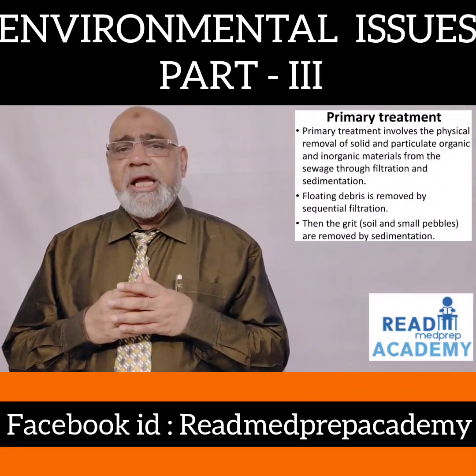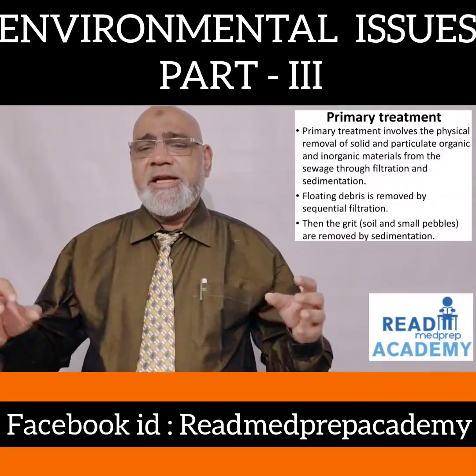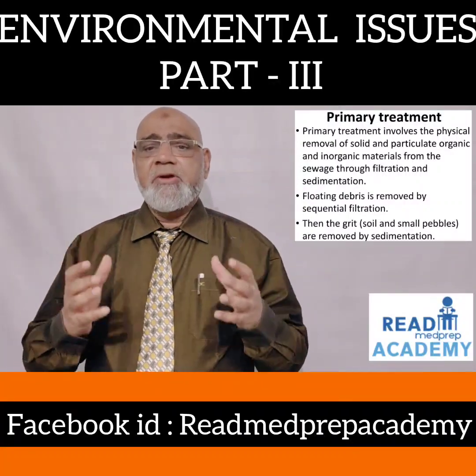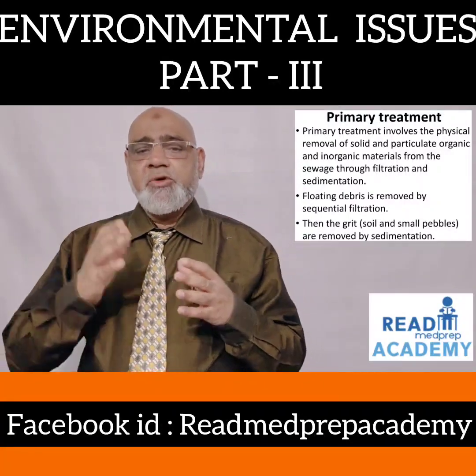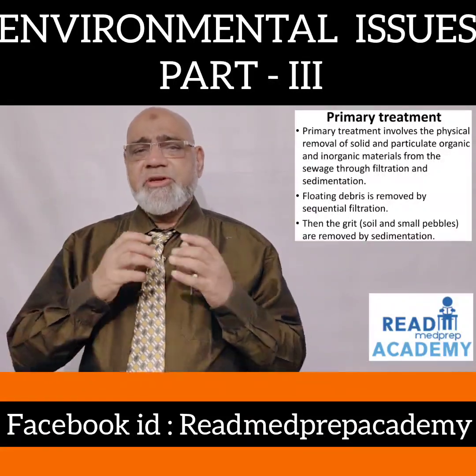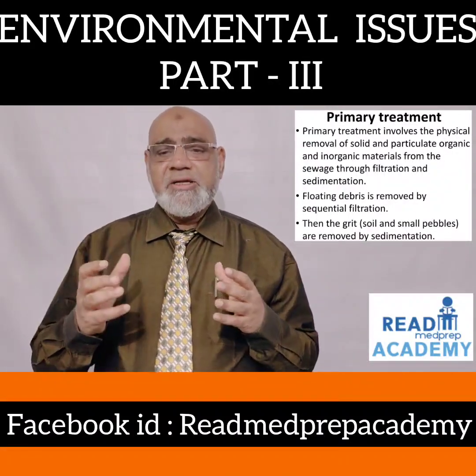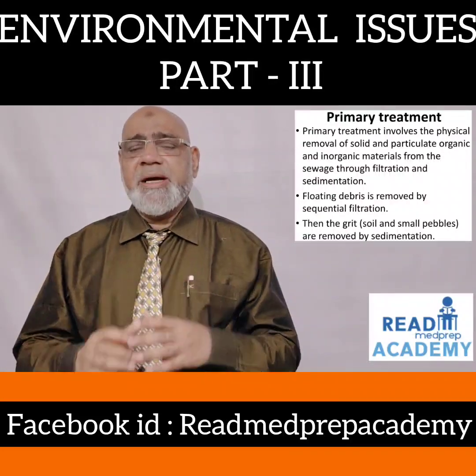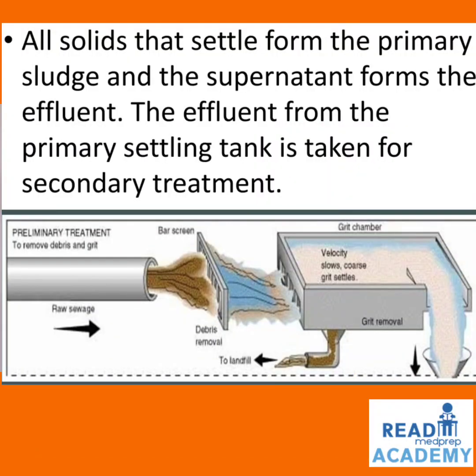Primary treatment involves the physical removal of the solid and particulate organic and inorganic materials from the sewage through filtration and sedimentation. Floating debris is removed by sequential filtration. Then the grit, soil and small pebbles are removed by sedimentation. All solids that settle form the primary sludge, and the supernatant forms the effluent. The effluent from the primary settling tank is taken to the secondary treatment.